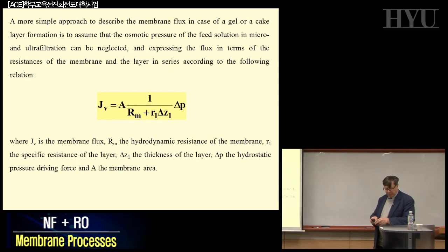Scaling is a term that is familiar to you because it's present in many other situations. It's also present in membranes. Scaling means deposit, for example, of calcium sulfate, carbonate, salts which are present in the solution. But in membranes, it's much more than this. The effect of scaling can be dramatic, blocking the operation completely, so we have to find a way to control it, assuming that our membranes are always working. As in the case I was showing before with seawater going across, there's no hole in the membrane. It's just that the flow dynamic of the system was not very well designed, and you have to change the flow dynamic, not the membranes.